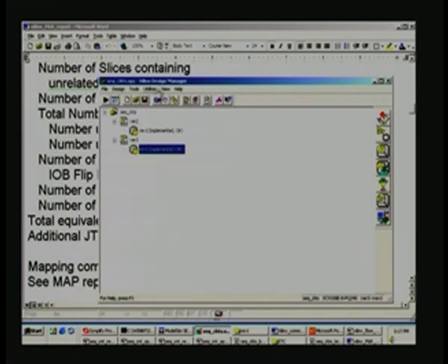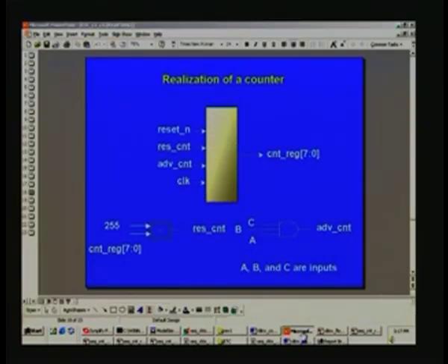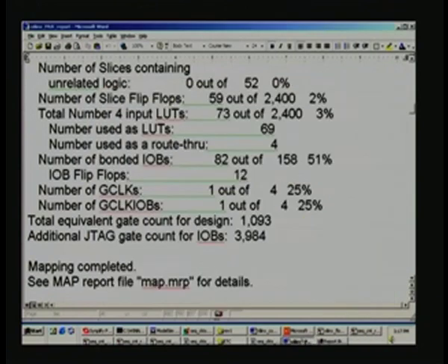From here we can see there is what is called utilities and one report browser there. If you click on this, you can get the report even after you closed it after running the place and route earlier, and you can click one after another and inspect all these reports, or we have already copied this log file here.